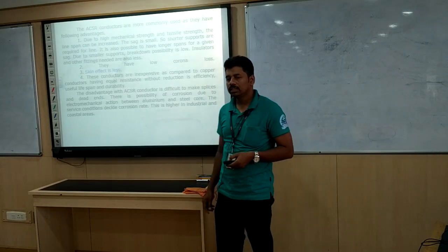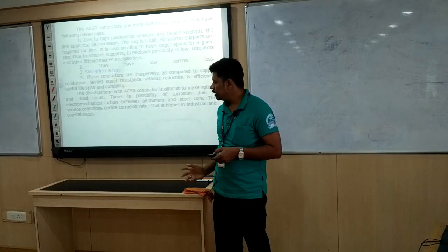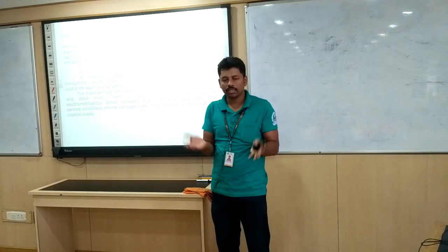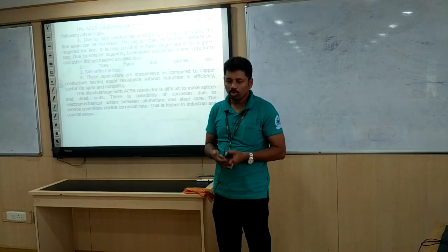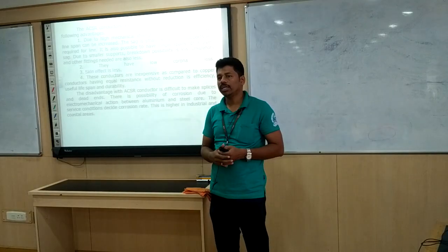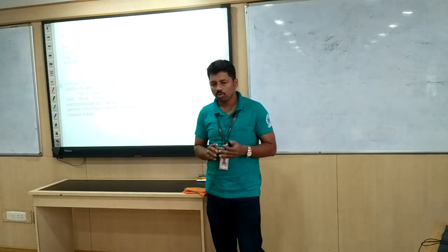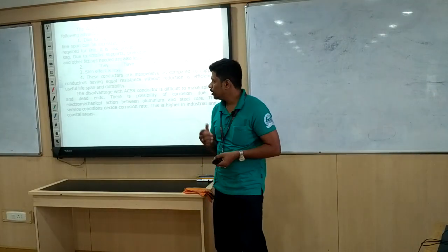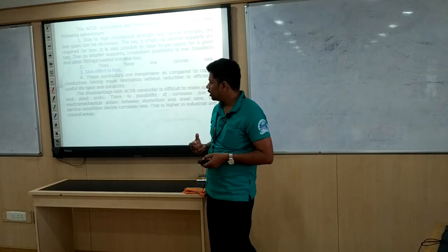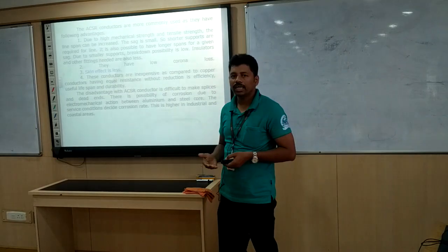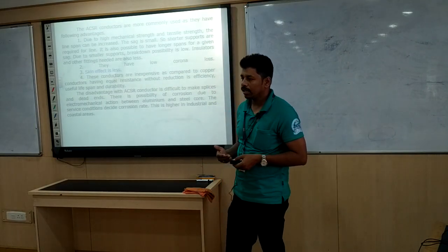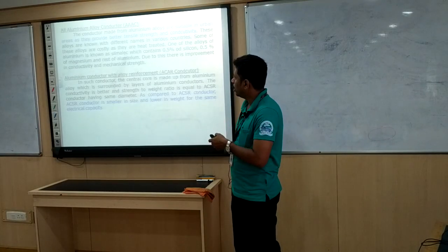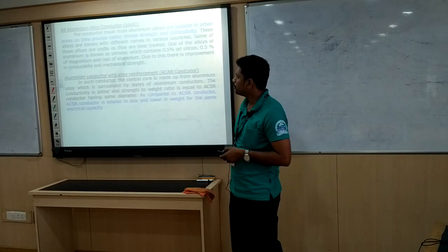What is skin effect? If you replace these conductors with a solid conductor, most of the time the current tends to concentrate at the surface of the conductor only. Due to that, we are not utilizing the effective area. Also, most of the time the outer strands or outer parts get punctured. That is called skin effect. To overcome that, we go for stranded conductors. Even that, nowadays, is replaced with hollow pipes to reduce the skin effect.